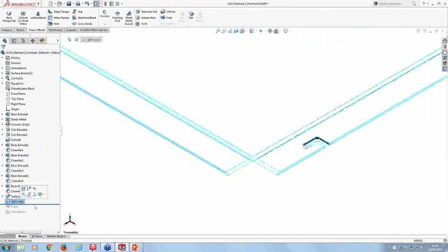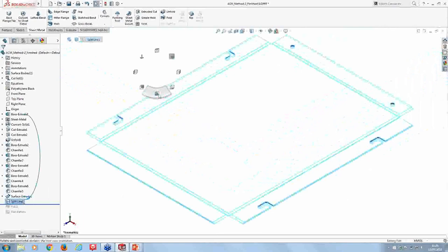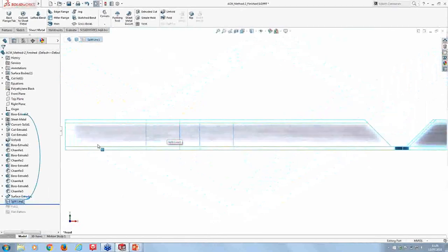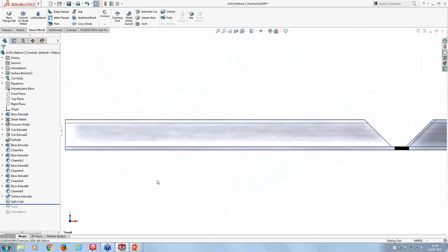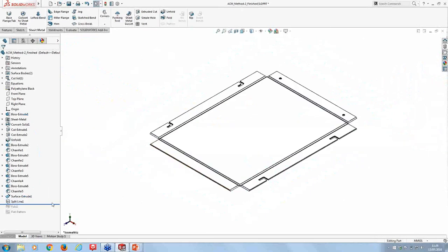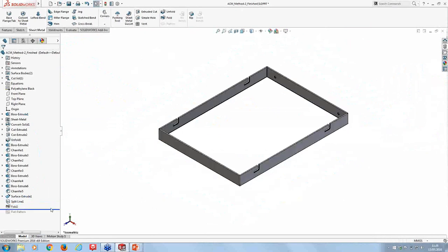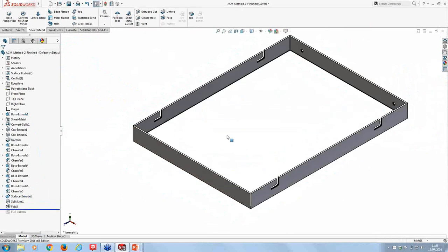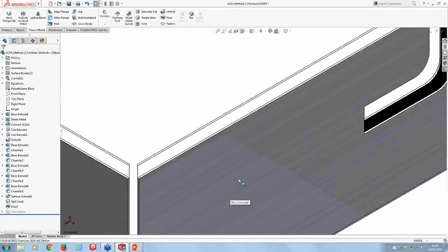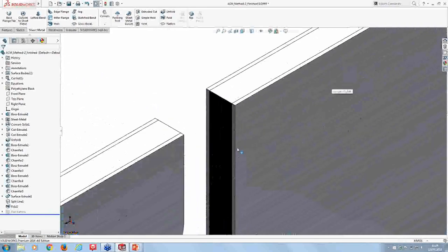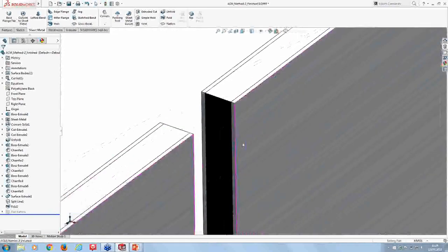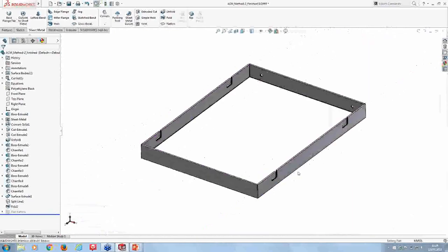All I've done here is I've just dragged two sketch lines through the model at the correct offset values to represent where the aluminium would be. Used the split tool. I've then done the fold operation, which we just saw, to fold it back up. And then I've just gone through using my appearances of aluminium and the black appearance as well to represent the core plastic in the middle. So that's two different methods we could employ to represent aluminium composite materials.